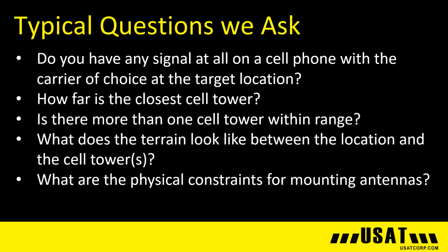When we have a client come to us for help in determining a successful LTE antenna solution, we typically ask these questions. Do you have any signal at all on a cell phone with a carrier of your choice at the target location? That's the starting point. And if they have full bars, we would usually go down one path.